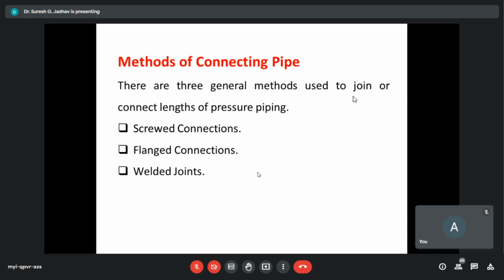So here we can eliminate or reduce the flanges and fitting components while using the weld joints or welded connection in piping systems. Therefore, we can reduce the cost of material, and the need for maintenance is reduced with the elimination of flanges and fittings.